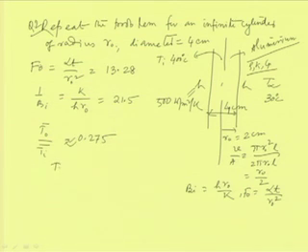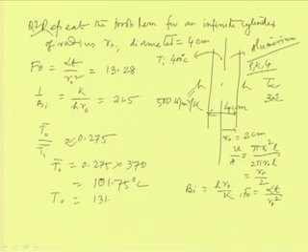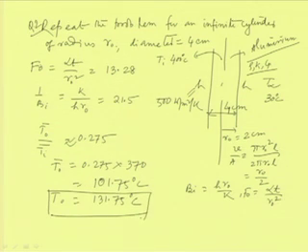Then T naught bar is equal to 0.275 times Ti bar, and we know that Ti bar remains the same as in previous cases, it is 370. Therefore, we get T naught bar around 101.75 degree centigrade, and so T naught, the center line temperature, becomes 131.75 degree centigrade. So, you can see the difference in the values with respect to the previous one. This is case A.